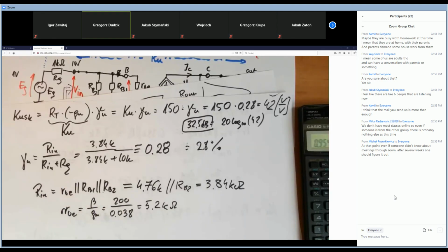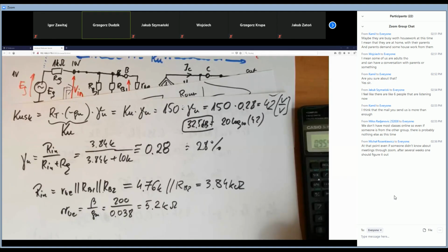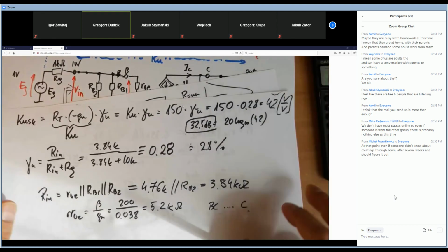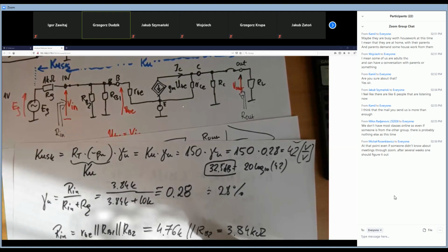So it should be, for example, a transistor with the letter C at the end of the symbol. For example, BC something, and C at the end. That means that the beta should be around 700, 800. That's the one case. Another is to choose the resistances correctly. However, in fact, the limitation is here.